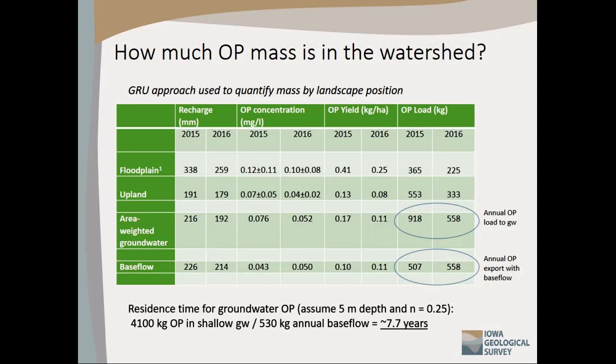Well, what is the likelihood of shutting off? Like 0? Because this is, again, restored prairie, and I was chatting with somebody over lunch, and I've probably put in several hundred monitoring wells across the state in different projects, and more often than not, we're measuring dissolved phosphorus or orthophosphorus. There's pretty much nowhere I haven't seen it less than 0.07 milligrams per liter. This is like in sand, tallgrass, or prairie restorations at Okoboji, it's 0.07. Like in cropland, it might be 0.15. We see it everywhere at about this rate.